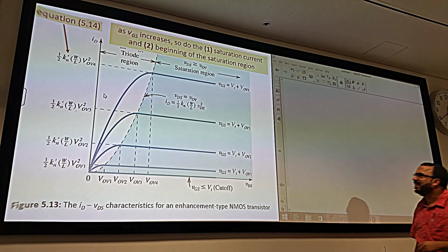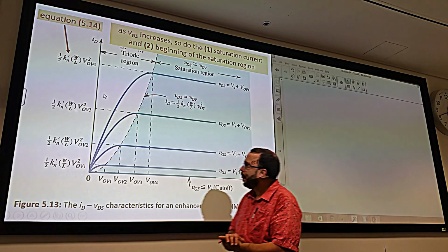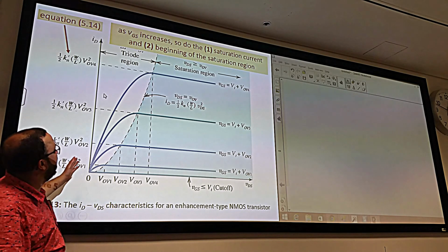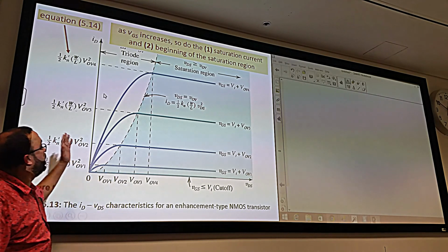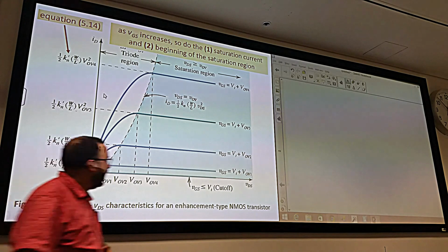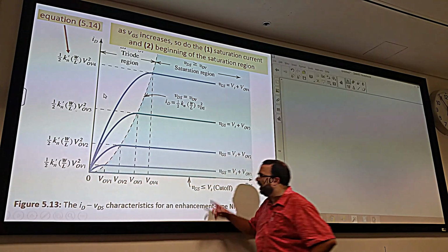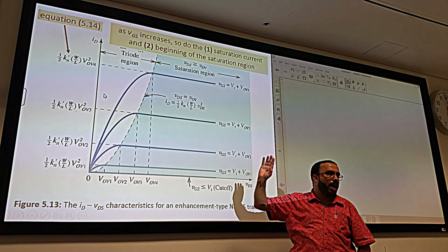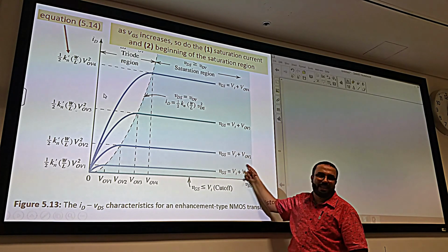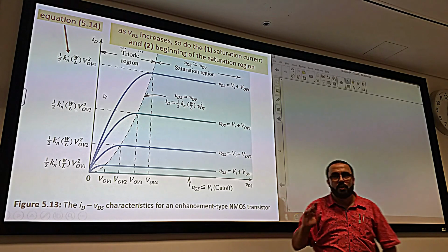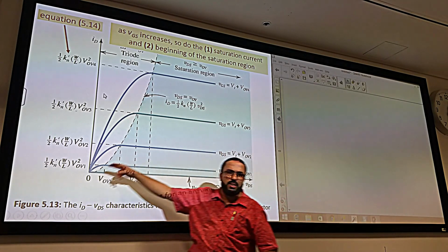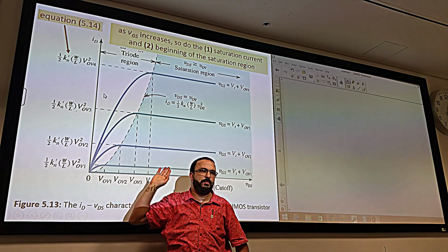Alright, good. Now, coming back to the MOSFET. The MOSFET will have its IV characteristic, that means ID versus VDS. It can be in any of these curves, but not all of them at the same time. Why? Because it will have only one overdrive, yes or no? So for any given overdrive, the MOSFET will be in one of these curves. That's it. As simple as that.